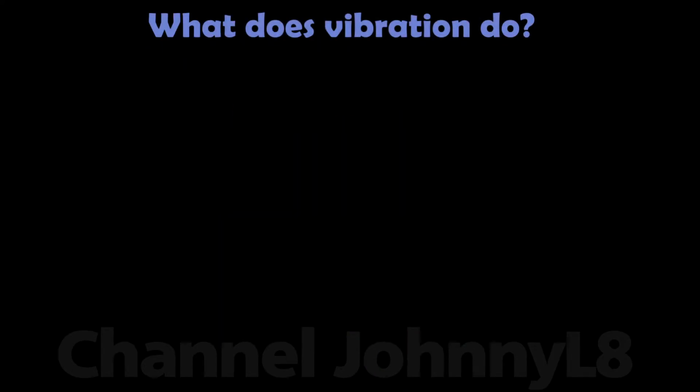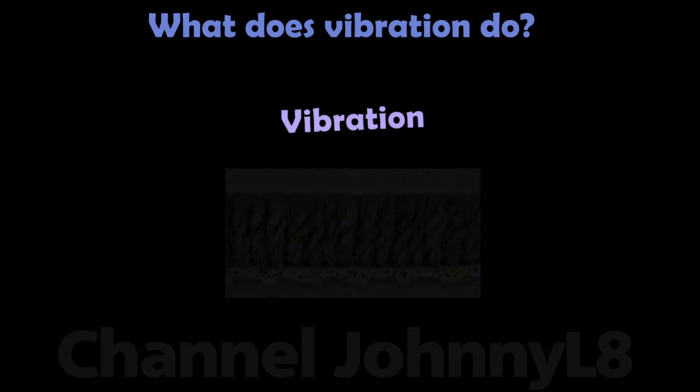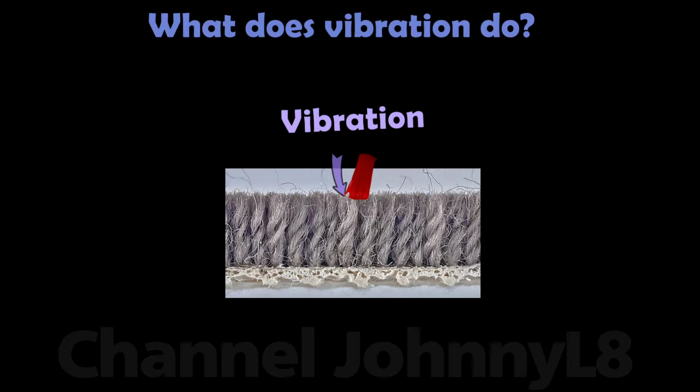Another method to assist dislodging trapped particles prior to pile spreading is to vibrate them loose. Impacts from the brush bar bristles can send out vibrations which can shake loose some trapped particles. Particles predominantly vibrate their way upwards because resistive forces are lower near the surface of the pile because the volumetric pile density is lower. Particles are much easier to remove from the surface layers, and so dislodging vibrations can assist and make suction through the pile more effective.